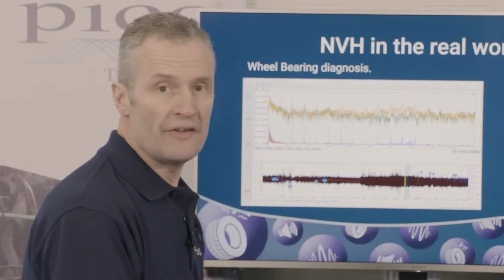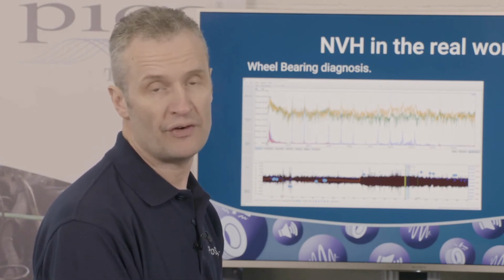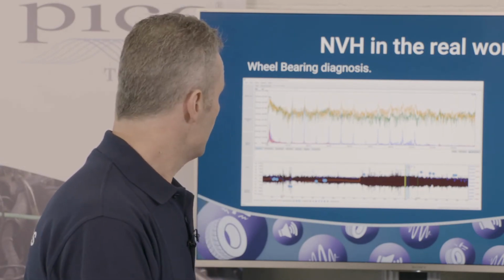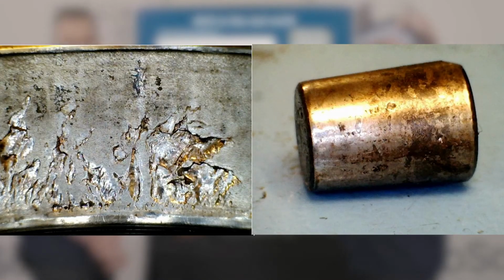We can qualify this by playing the audio back and listening to the microphone on the left hand, comparing it with the microphone on the right hand. But really what I wanted to talk about is the complexities of wheel bearing diagnosis. Just look at the contamination and the debris on the bearing there, the roller and the race, and the possibilities of multiple vibration orders from just one bearing.